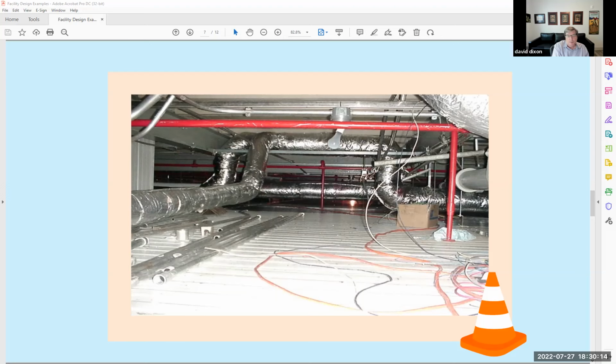Right. And my rule of thumb is if you have 3 foot clear to the beam, you have a little bit more to the trusses. But if you're 3 foot clear to the beam, you're already in trouble. You need about 4.5 feet to the first obstruction to run your mechanical, electrical, and fire protection systems in that interstitial space. You also need to ventilate it and heat it sometimes, and to avoid moisture and condensation in that interstitial space. But that one's hard to operate in, and could very much be a safety hazard.